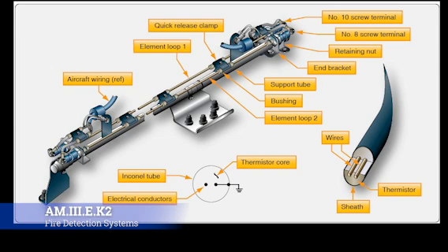So it can get hot and then set it off, or it can get to a certain level of heat, and then it's going to just immediately set it off because they know there's a problem. The system resets automatically when the conditions normalize and can distinguish shorts from actual fires based on the resistance change. Now, all right, so the dual loop configuration, just like the fin wall system, works the same here. So it can be just as robust.